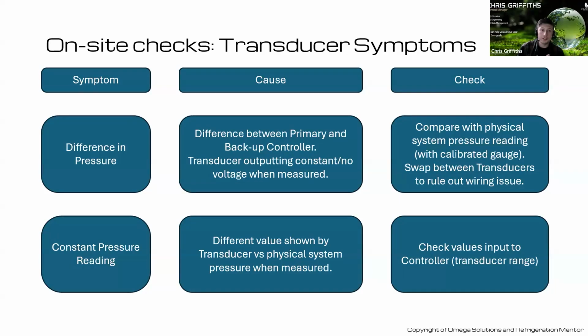And yeah, basically just do your checks and do your due diligence. I think that is important too, is to understand the system you're working on, because there's so many. I train so many people from around the world in different countries, and we're learning CO2, and like you just said, most of the systems you see now are 60 bar, right? 800-some PSI standstill pressure. All the ones here in Canada, I don't know many that are that high. There are some, but most of them are 40 bar systems, standstill pressure.